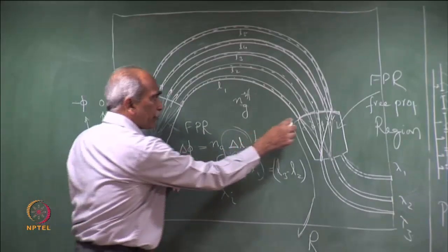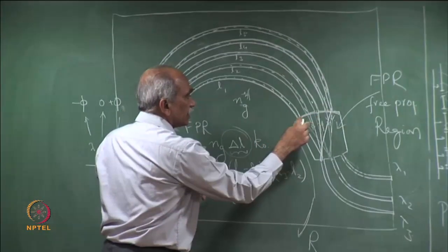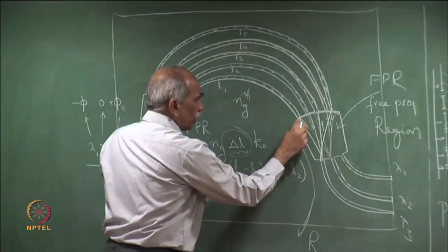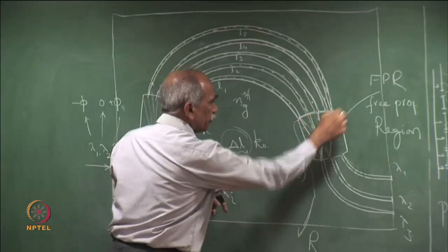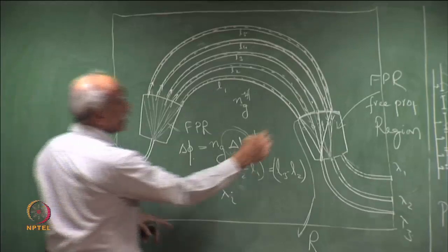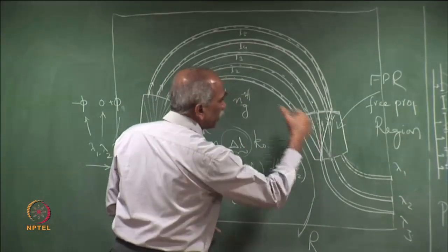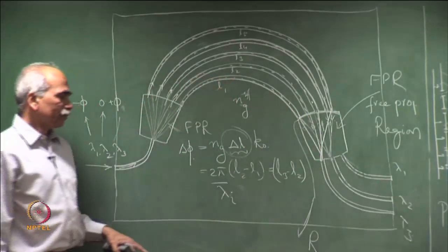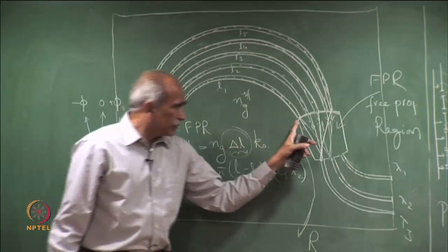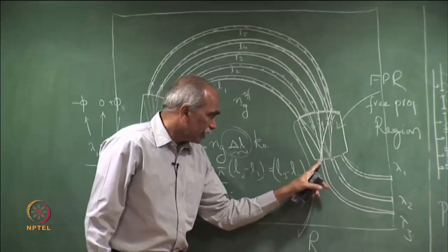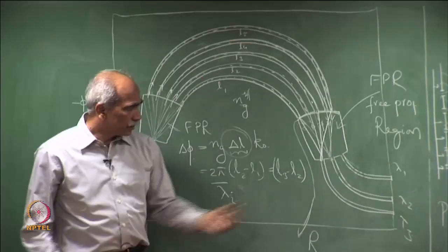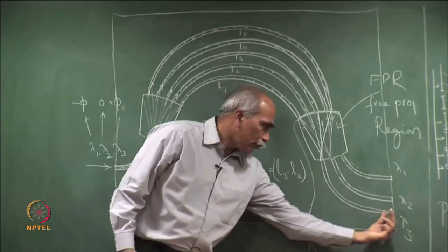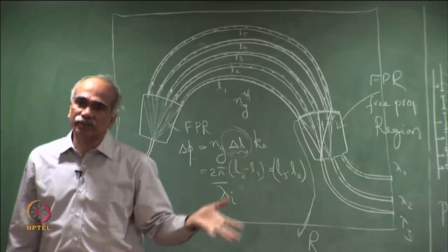It is constant from one waveguide to another in the array; adjacent waveguides have the same phase difference, but that phase difference is different for different wavelengths, and therefore, the output will focus at different spatial positions. Accordingly, the location of the output waveguides is positioned.